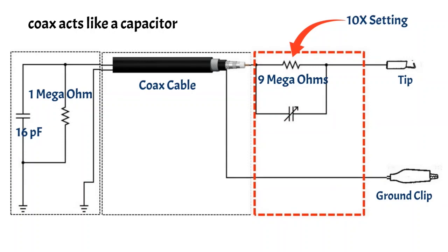You could learn much more about these filters in semester 4 under the circuit theory module if you were selected to the electrical engineering field. To fix this, 10X probes include a variable capacitor in parallel with the 9 MΩ resistor. This is used to compensate for the low-pass filter. This will keep the signal attenuation more or less the same across all frequencies.